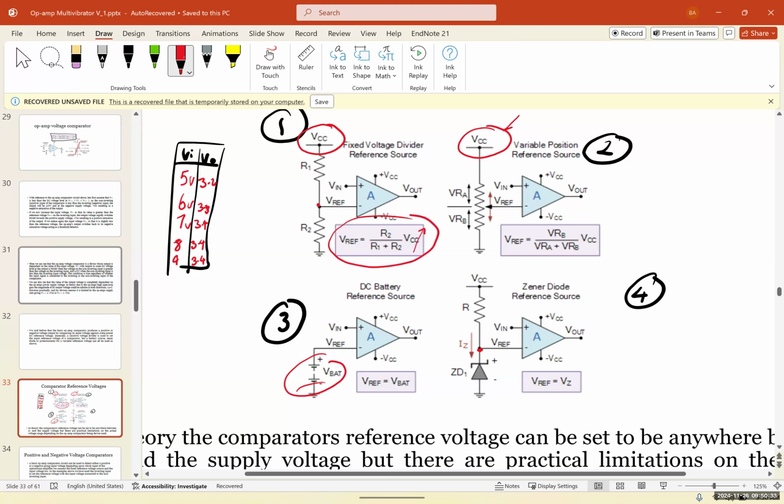What happens to the reference voltage? The reference voltage also increases. And what happens when VCC drops? The reference voltage also drops. So if it's connected to the battery you're using at night, the battery is draining, and with it, you're reducing the reference voltage. During the day, when the battery is charging, the reference voltage is going up with it. So the battery itself is creating a variable situation, and it's changing the reference voltage.